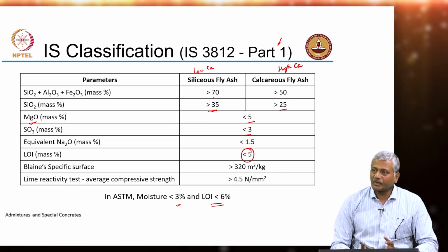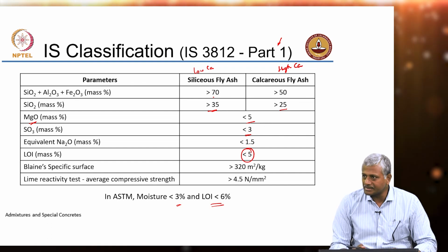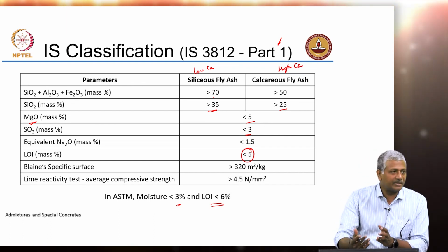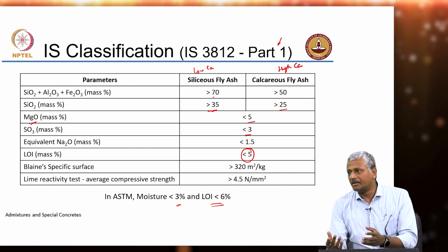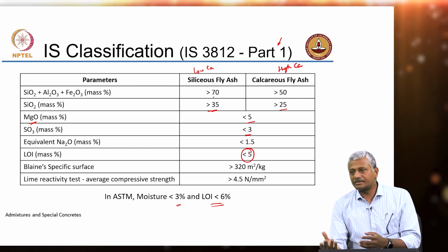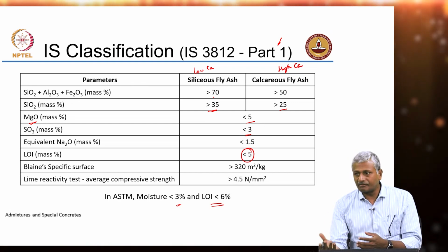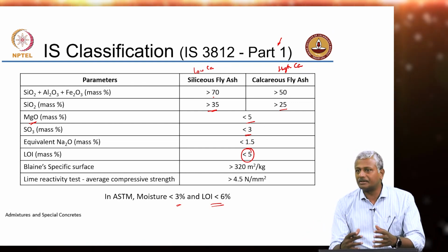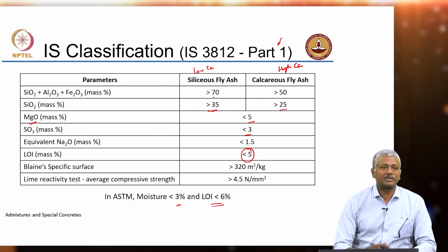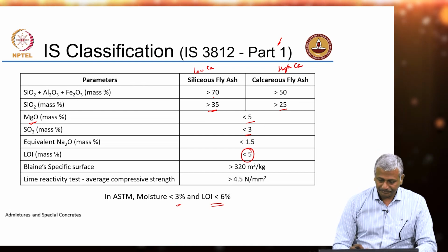So, that is why we talked also about the modified test, modified R3 test, or the R3 test, where we use a modified system, not just lime, but we also mix some alkalis, sodium, potassium hydroxide and so on, and sulfate and carbonate to simulate a realistic cementitious system, so that that activation can actually happen in this pozzolanic material.